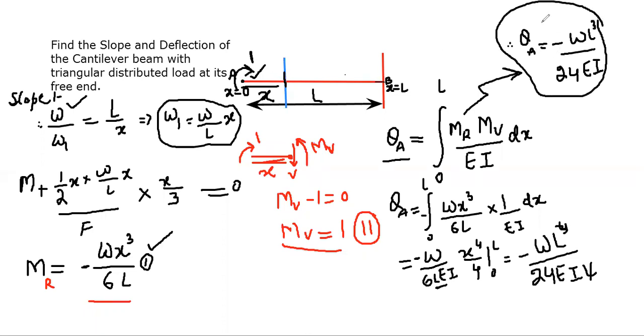This is by what method? This is by the method of virtual work. Okay, this is how we have to find it. So the question was that we have to find the slope at point A. Wherever you have to find the slope, maybe here at point C, assume a bending moment of 1 unit, clockwise or anti-clockwise, there.